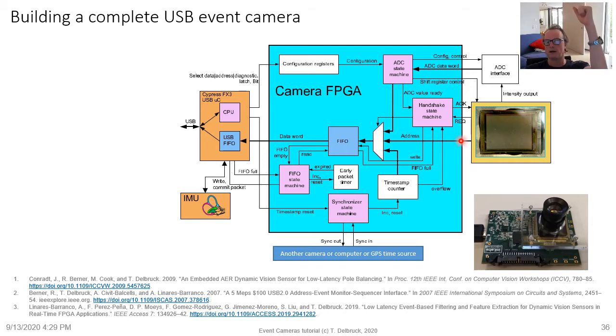You go up one side, the other side, and then down, and then down, right? So up, up, down, down, like that. That's why it's 4-phase. Simplest possible handshake. But on the input to this handshake state machine, because this is asynchronous, you need a series of 2 D flip-flops that are clocked by the system clock here to make sure that the logic system here doesn't go into meta-stability. So that's one interface.